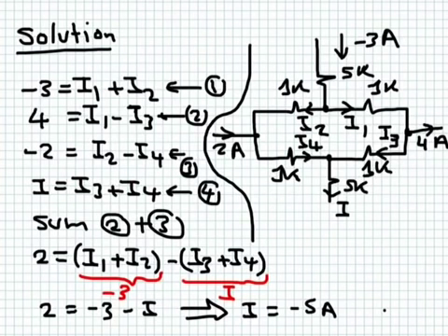And then the last equation, and this is why I selected the direction of I3 and I4 this way, because these two currents are summed at this node to give us I. So I, which is the only current flowing out, is equal to the sum of the two currents flowing in. I is equal to I3 plus I4.